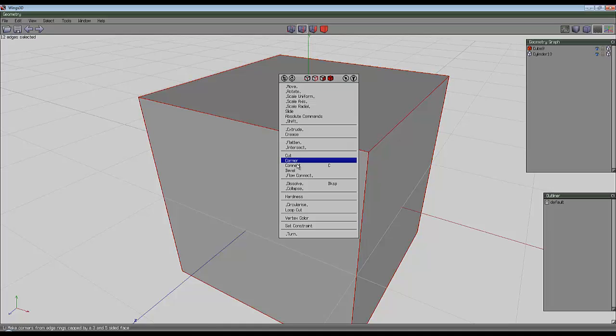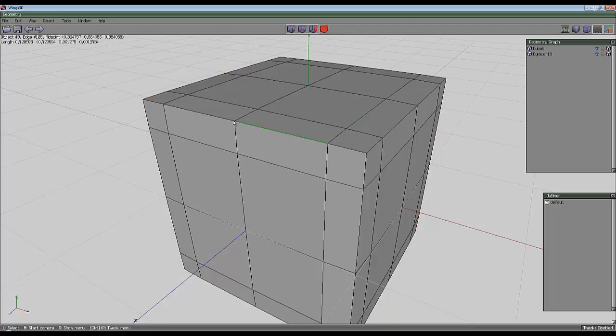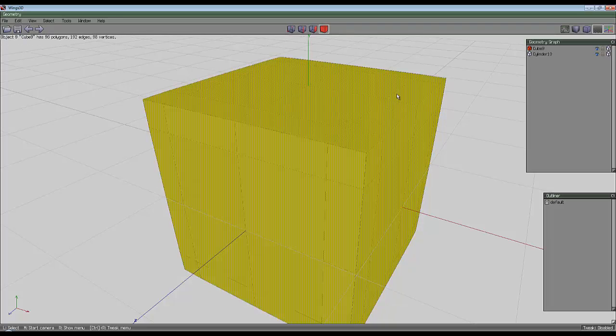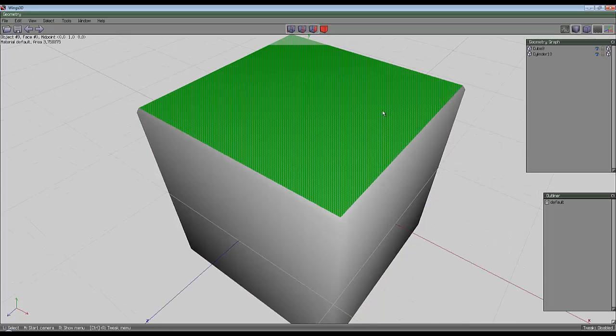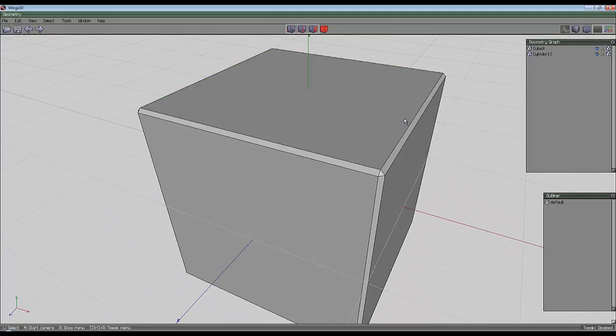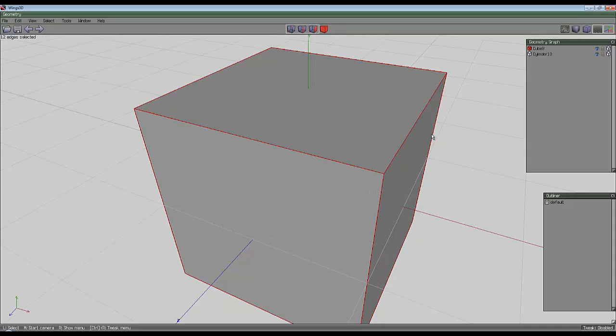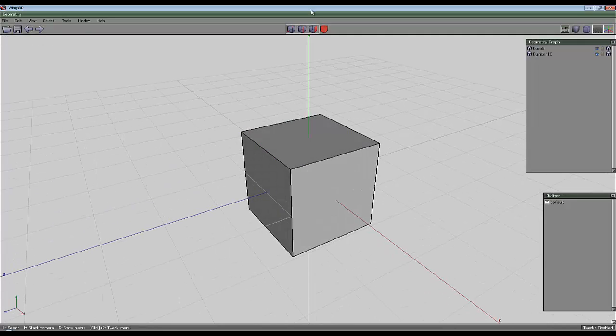Well, I could try beveling each corner, and then when I smooth that, you can see that the cube shape is retained. However, under these circumstances, when it's not smoothed, the faces are still not looking flat. So there's something a bit iffy about that, which I don't really know the answer to, but it's certainly not right. So let us try supporting the faces in a different way.